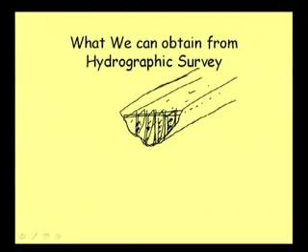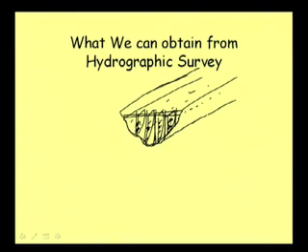Now, based on this average velocity, we can calculate what kinetic energy is flowing through this section. As we explained already in the last class, if we calculate the energy based on the average velocity, here again we introduce some error, and that is why we need to know the value of alpha, that is the velocity coefficient of this section.